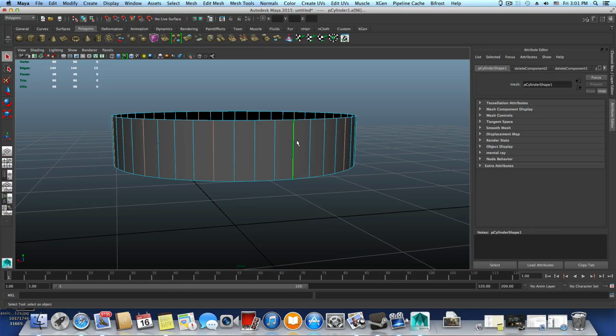Now this is also the time to tell you that whatever you're gonna create here, the thickness of your net is what will determine if the net will be assembled correctly to your holes, those little holes we made sure that this spring is going through, this tunnel. Anyway, the connection point distance will always be the same if we control the radius, the same radius. So you don't need to be worried about this, but the thickness of the net is what counts and can cause problems later on. So this is pretty much experimental for you as well. I can't promise you that it will fit correctly and everything will be fine, though try to experiment and use just slightly different values than what I do.